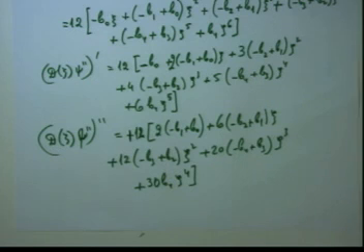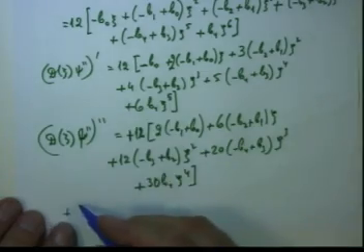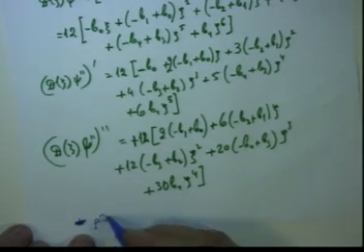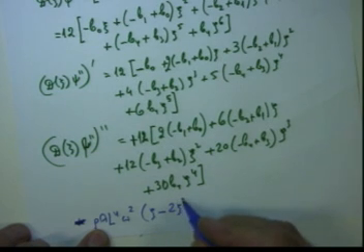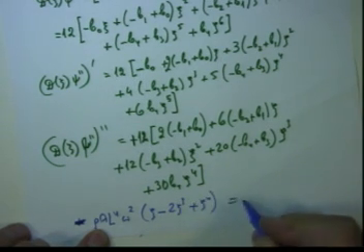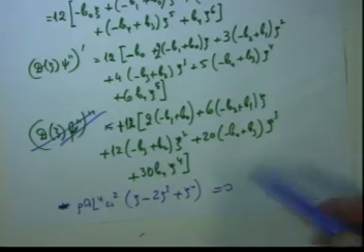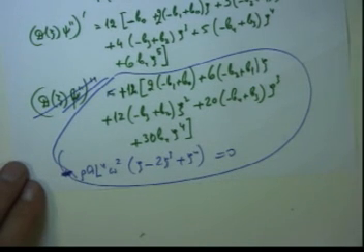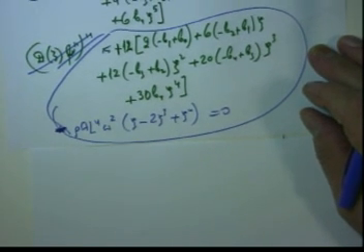So now we have to add here that expression that we had here, this one. So then it is minus rho A L in fourth power omega squared times psi minus 2 psi cubed plus psi in fourth power. This equals 0, and this should be taken out. So now we have this expression. Okay? Now we have to diligently evaluate everything.